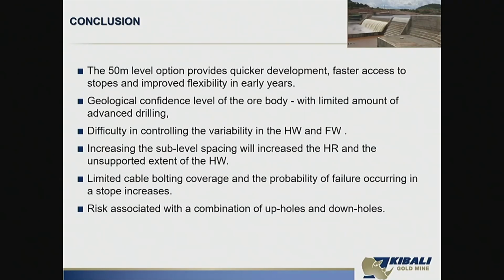So in conclusion, the 50-meter level option provides quicker development, faster access to the stope, and improved flexibility in the early years. But the biggest problem is geology. As I said, geology is king. You have to make sure you understand your geology, otherwise you don't have a mine. So with a limited amount of drilling, you're really dealing with the unknown, because if anything changes in the footwall or the hanging wall or the geology itself, the geometry, it becomes very difficult to manage from a stope design perspective.